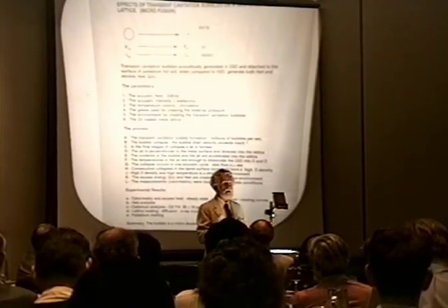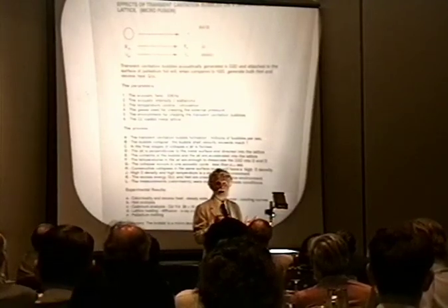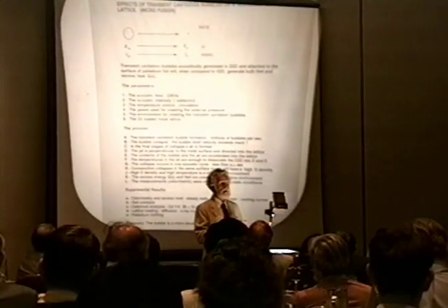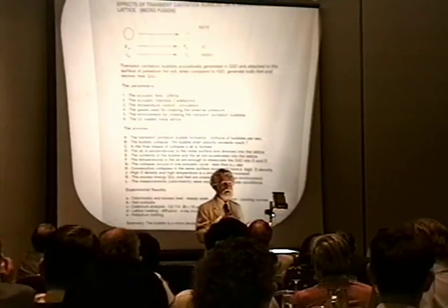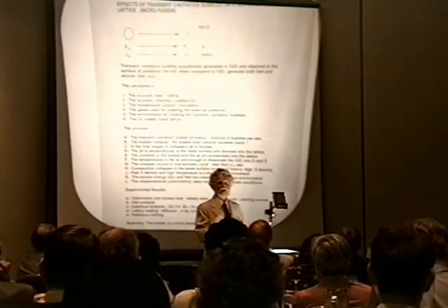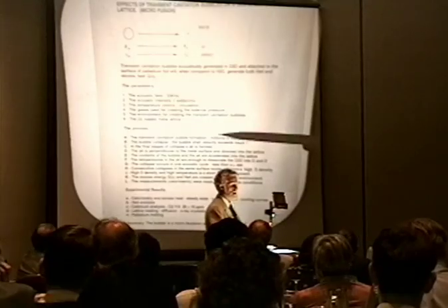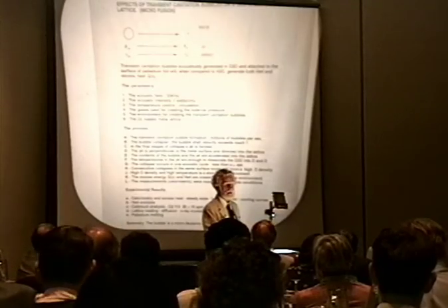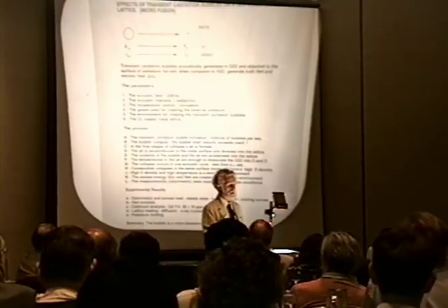It's very important to keep the temperature and the pressure at the correct values so that the cavitation will occur. If the pressure is too great, then we dampen out the cavitation. If the temperature is too high, it'll just foam. So you have to be careful about that because we're putting quite a bit of heat in here. We have to put the liquid through a heat exchanger to remove the heat as it's made.